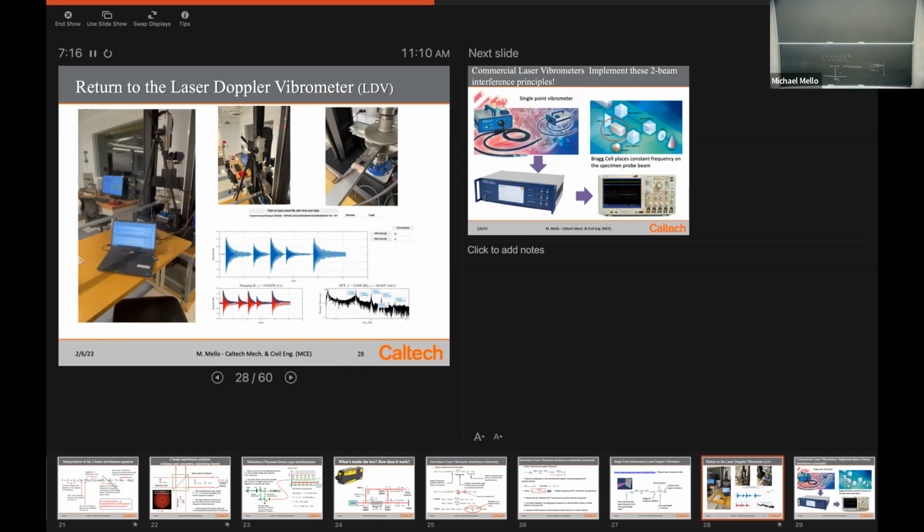Now, this is just a spectrum where we say, hey, give me a spectrum of this signal. If you were interested in decay time, you could certainly look at this decay time and look at the damping characteristic of your structure. That's a very valuable thing to study. Okay, we want to know how quickly things quiet down, right? Another thing then would be, what are the dominant modes or frequencies present? Okay. All right, so that's just an example.